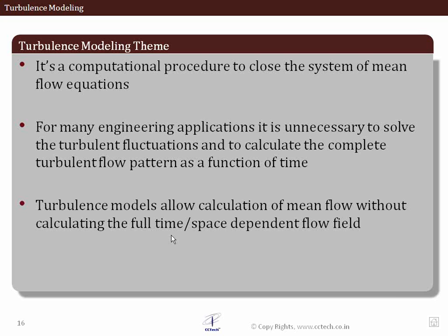In turbulence modeling, we should also be aware of the procedure. The procedure is that we try to close the system of mean flow equations. We look at what exactly these mean flow equations are, and most of the time for engineering applications we don't need to resolve each and every small eddy. We don't need all the flow fluctuations as a function of time and space, but we can try to model them and get the effects in terms of quantities like pressure drop and enhancement in the mixing characteristics. The turbulence models also allow for the calculation of the mean flow quantities without resolving it completely to the greatest minutest detail.